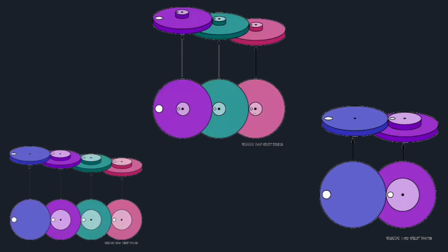And using that multiplier, you can calculate the gear ratios for an array of gears with the same ratio between each other. And as a result, what you can do is use a set of gears to increase either the speed or the torque outputted in a way that is more practical. For example, you definitely will not be able to just scale up your gears as much as physically possible in a realistic mechanism, such as a robot, right? There are size limitations. So instead of doing one gear to get all the force you need, you increment it by having multiple sets of gears.